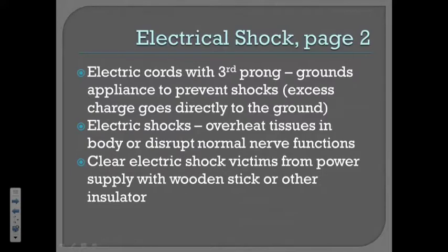You need to push them away from it using some sort of insulator, like a wooden stick. If you happen to have maybe something gigantic and rubber, use that. But whatever you do, don't just go up and grab them, because you're going to be in the same situation as them. You need to find some sort of insulator and knock them away, knock them onto the ground, away from that wire the best you can, so that you are not harmed also.